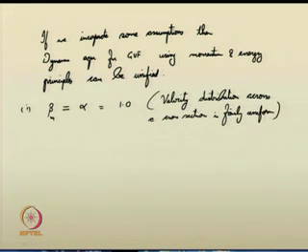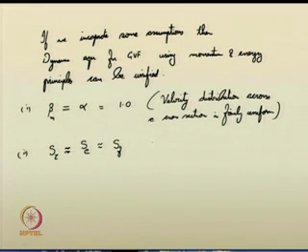So, if we can incorporate this assumption, another assumption we can suggest is that if the shear slope S tau can be approximated as the energy slope, both of them can be approximated as the friction slope S f. If we can do that, it will help us in further unifying the dynamic equations of gradually varied flow. So, we can see that friction slope is the one which is used in Manning's equation.